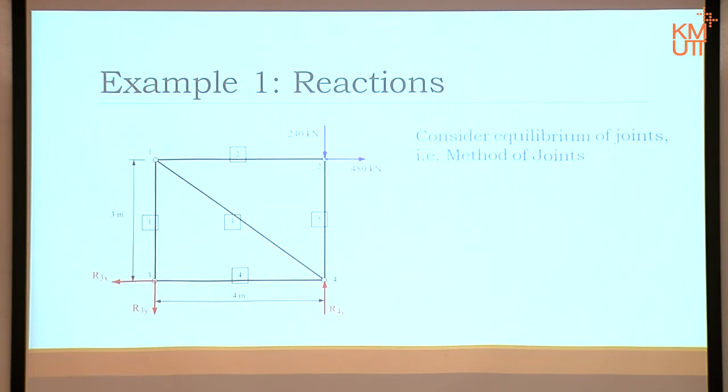In this analysis, it is very helpful to analyze which direction the force goes first, because these values will be repeatedly used, meaning you calculate one and you're going to use it again. If you calculate negative all the time, it causes more problems. It's easier if you analyze the direction first and keep calculating positive.